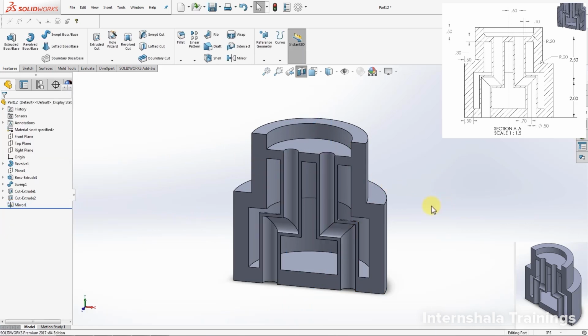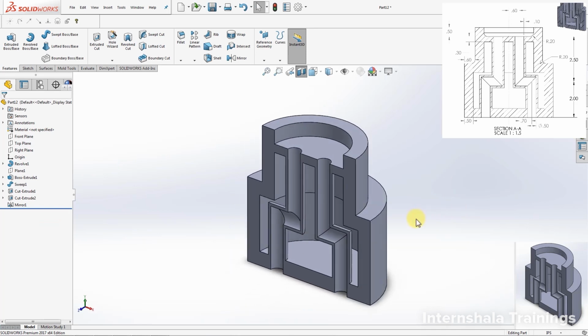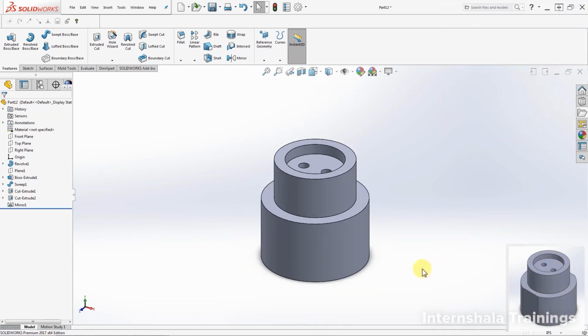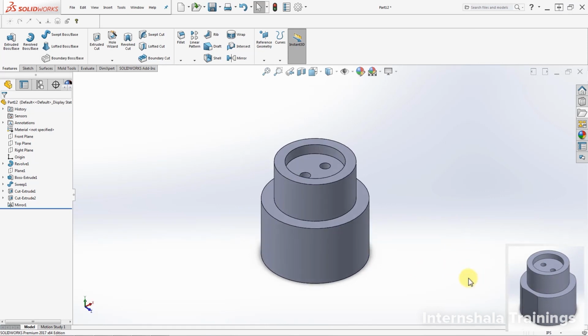So now we have just done our third stage. Let's go ahead and exit the cross-section mode. Now let's go ahead and create the slots in our fourth stage. Those slots are about here. One is here on this side and one in the other side. There is no plane here, and so we are going to have to create a new plane for it.